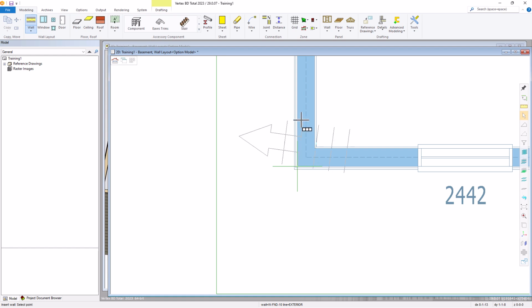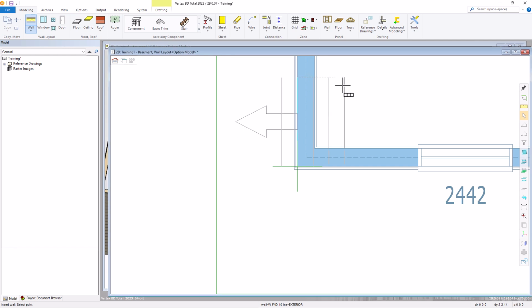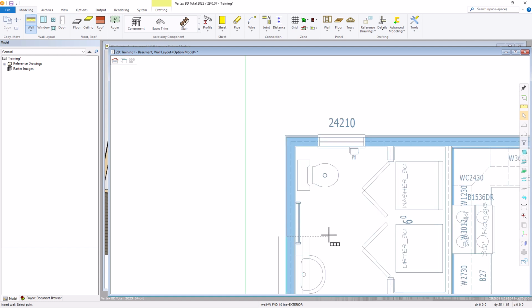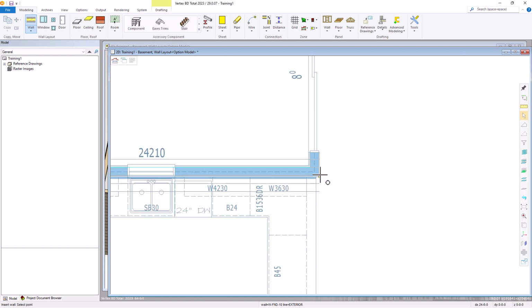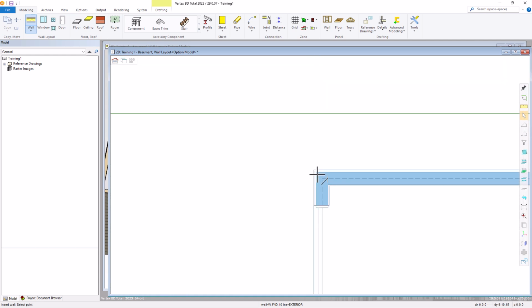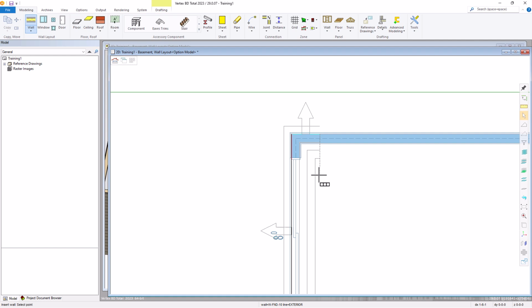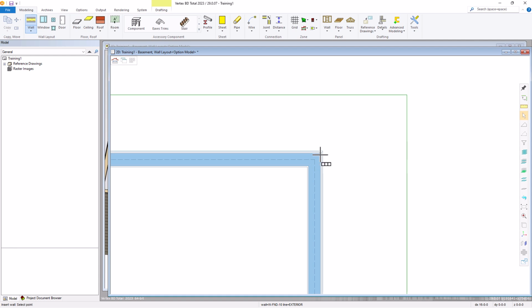We're going to use the exterior corner. I'm going to lock this vertically using the lock cursor vertically. That way it alternates horizontal and vertical as we're picking our points. So first one is vertical. I don't have to worry about the constraint. It's doing it automatically. So pick that point. There's also a pan feature where you can hold shift and your middle mouse button and pan over. I personally just zoom back, zoom out, and zoom in, but whatever method works for you.